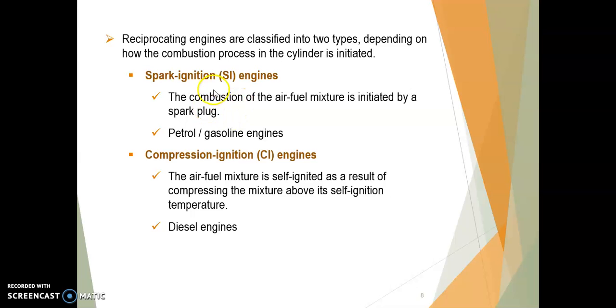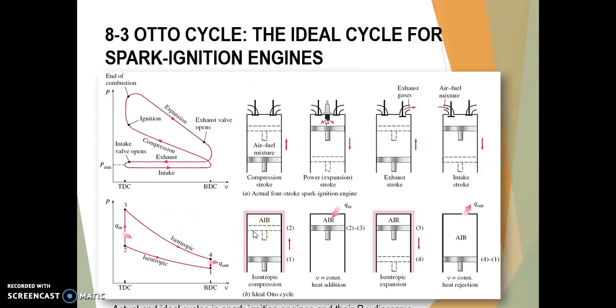Then it will convert the whole gasoline to a fire that will force the piston to push down and rotate the crankshaft. The other part is compression ignition. This one is about the air-fuel ratio that will be moved inside the whole system. It will be compressed until it reaches above its own self-ignition temperature. Then this one will be applied in the diesel engine.